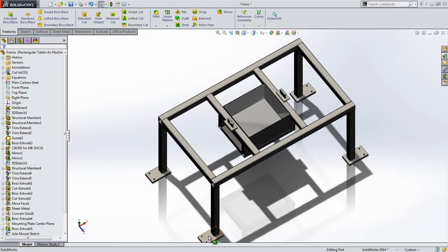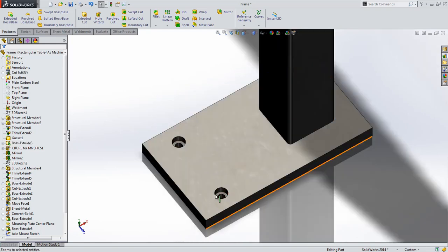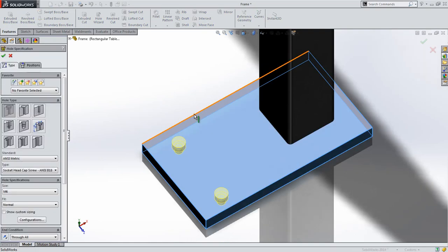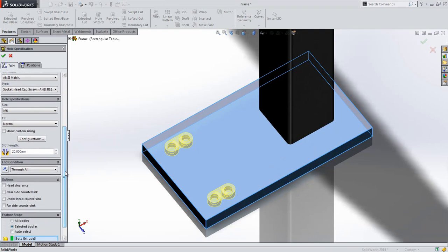When adding holes for fasteners, sometimes a slot is a better choice, as it allows for more tolerance in mounting conditions. The Hole Wizard in SolidWorks 2014 now supports slots. Specifically, it supports three types: slots, countersunk slots, and counterbored slots. When this hole is changed to its slot counterpart, there are options to control the slot just like a hole.